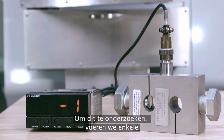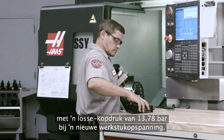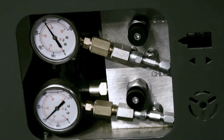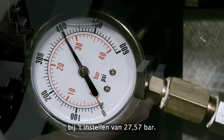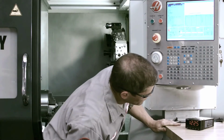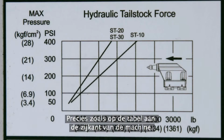To explore this question, we're going to perform a few more of our famous real-world tests to demonstrate why we here at Haas recommend starting with a tailstock pressure of 200 psi when setting up a new part. First, it's helpful to figure out how much force is actually being applied when we set the tailstock to 400 psi. Using this load cell, we can see that our max tailstock pressure at 400 psi translates to a little over 1,200 pounds of force, the same as what the chart on the side of the machine says.